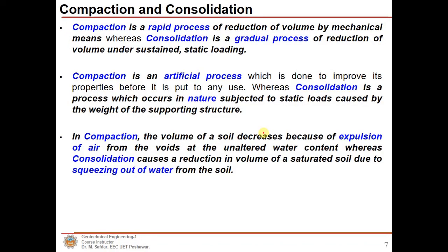Now, what is the difference between compaction and consolidation? Compaction is a rapid process of reduction of volume by mechanical means, whereas consolidation is a gradual process of reduction of volume under sustained static loading.